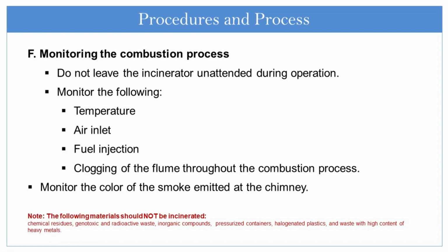Monitor the combustion process. Do not leave the incinerator unattended during operation. Monitor the following throughout the combustion process: temperature, air inlet, fuel injection, and clogging of the fumes, and monitor the color of smoke emitted at the chimney. You can find a note in red at the foot of this slide. It is a caution: do not incinerate the following, including chemical residues, genotoxic and radiotoxic waste, inorganic compounds, pressurized containers, halogenated plastics, and waste with high content of heavy metals. They must not go to the incinerator. So if they are there, do not incinerate them.